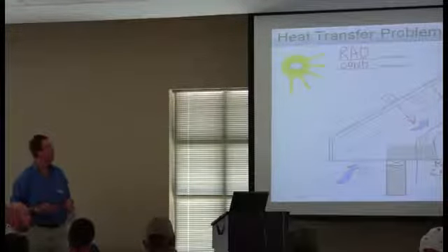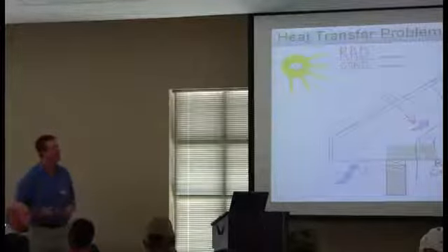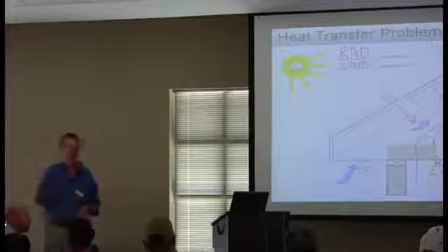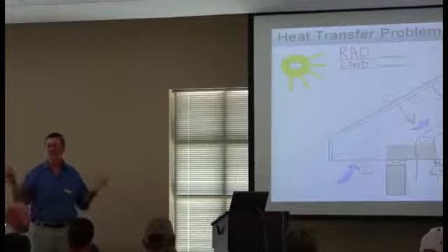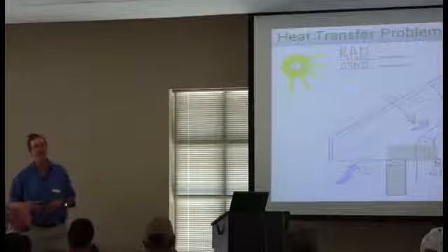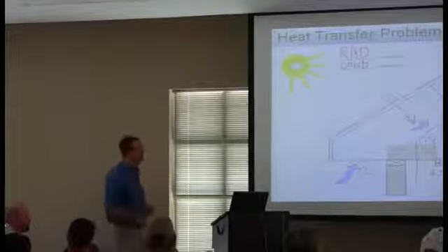The only time somebody whined a lot and said, okay, but what if I want a solar powered fan? It's like, fine, okay, fine, but still don't do it. Don't use a vent fan on an attic. It just sucks conditioned air into the attic.